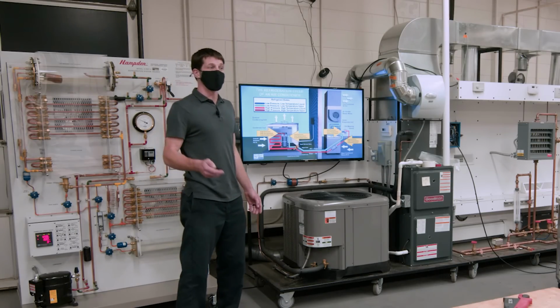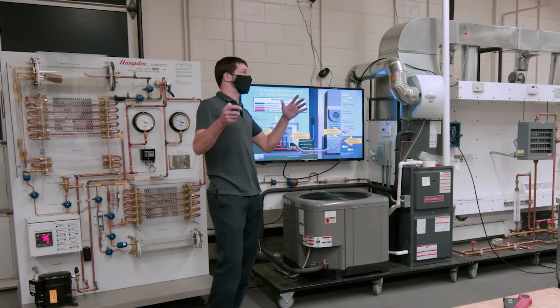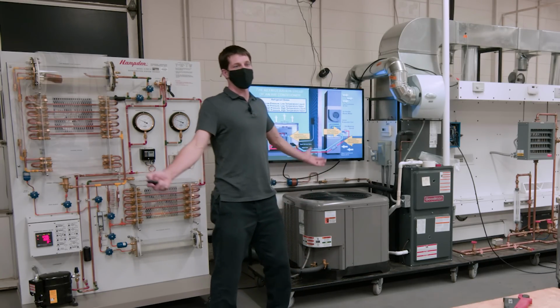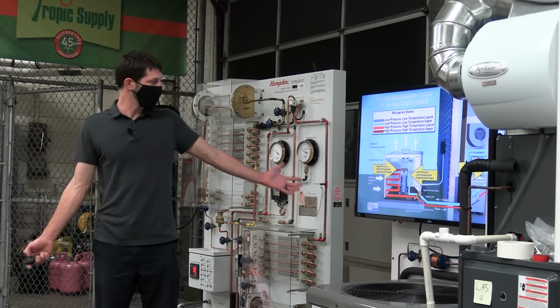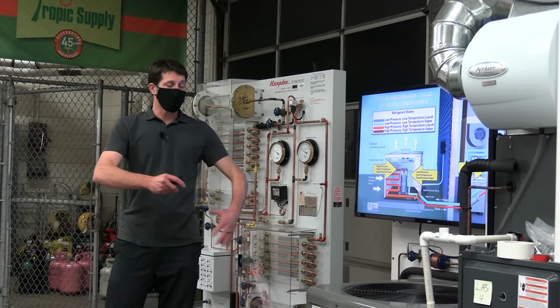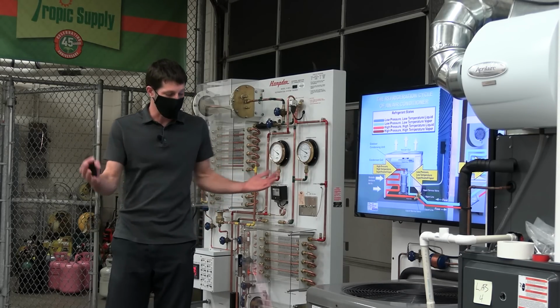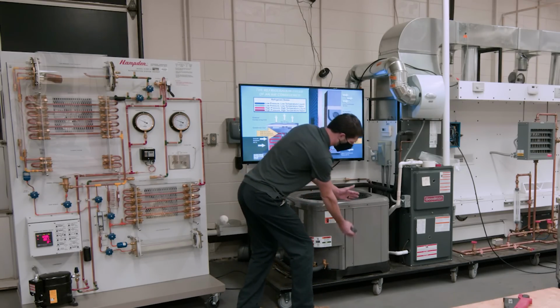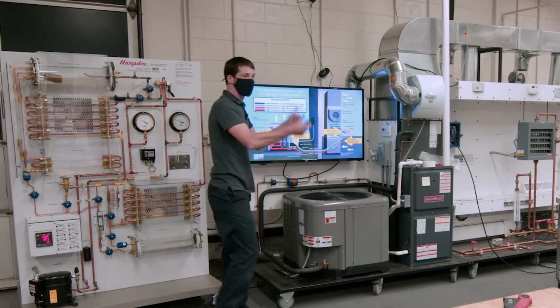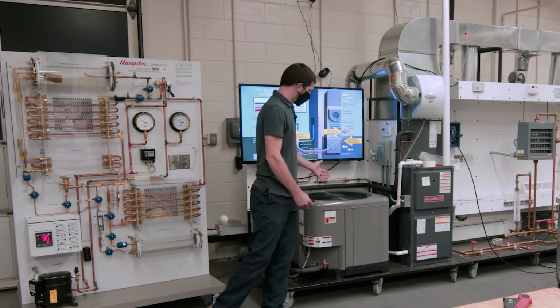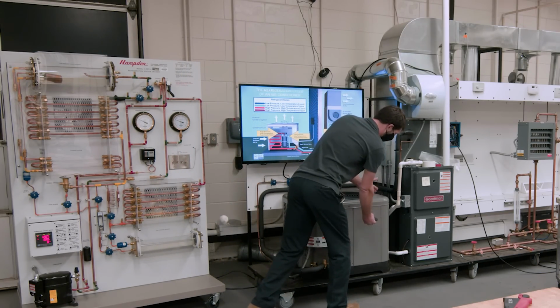So a lot of times people ask me, that's great, I don't care about your subcooling and your temperatures and stuff. What pressures does it run at? I'm like, man, I can't tell you because it depends on the day. You could totally overcharge a system and it's not going to perform effectively because you just overfilled this whole condenser coil. When you overfill this, the pressure out here is going to be dramatically higher, and you're going to be drawing a lot more electricity because the whole thing is filled.